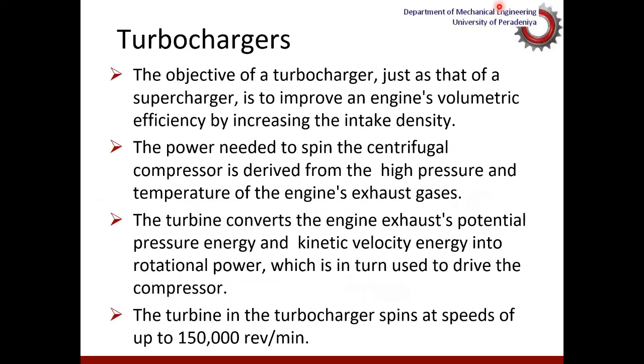Now, as in the case of supercharging, the main objective of turbocharging is also the same, just to increase the volumetric efficiency. The only difference, as we looked at earlier, is that in turbocharging the compressor is driven by the exhaust gas. So the temperature and the kinetic energy in the outgoing exhaust gases, as well as the pressure energy, are used as a source to drive the turbine. Usually these turbines run at speeds of around 100,000 to 150,000 revolutions a minute.